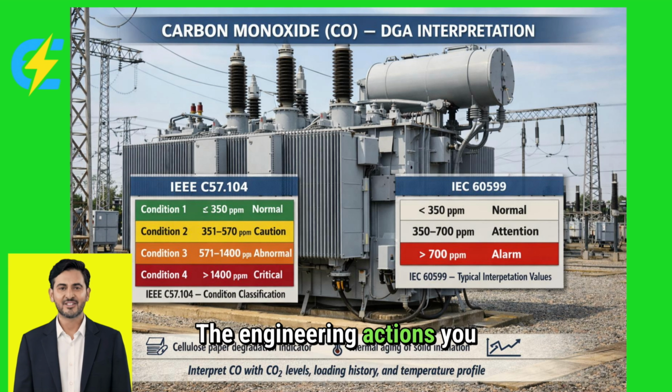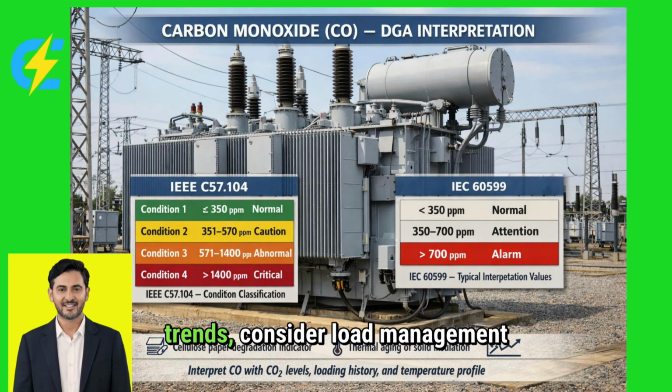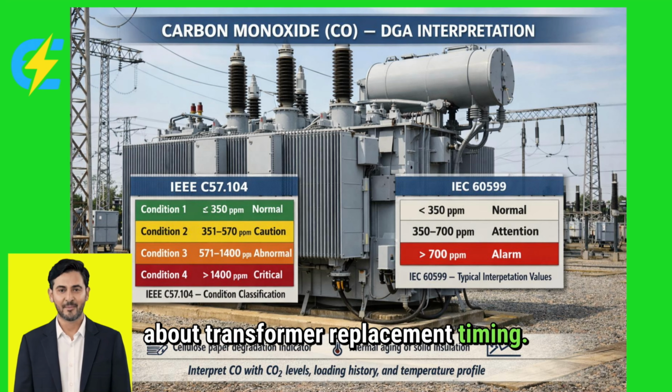The engineering actions you take based on carbon monoxide trends can significantly extend transformer life. When you see increasing trends, consider load management to reduce thermal stress. Implement more frequent oil processing to remove moisture and oxidation products. Plan for insulation drying if moisture levels are high. And most importantly, use the carbon monoxide data to make informed decisions about transformer replacement timing.